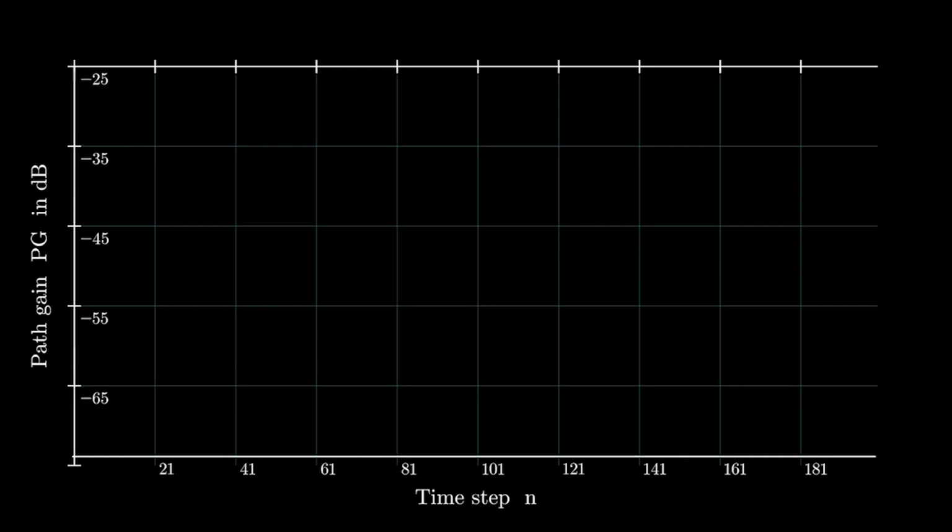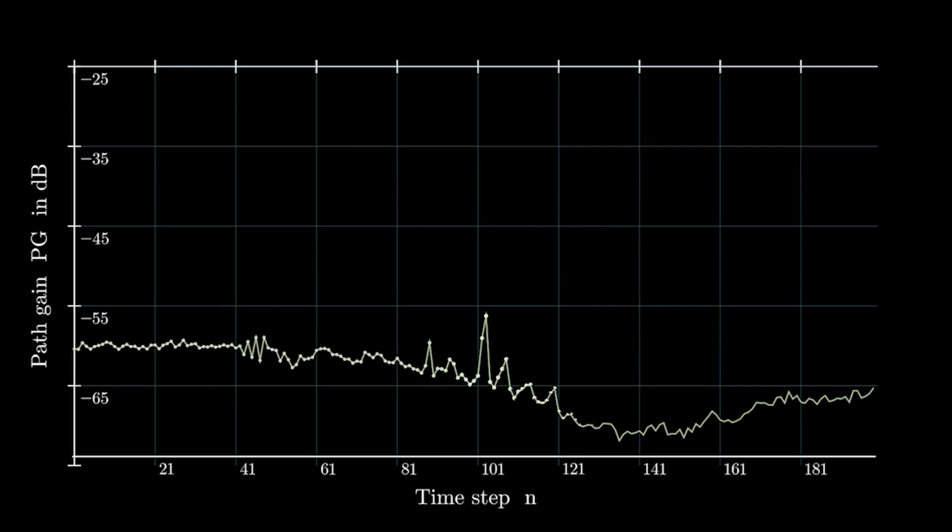The efficiency of phase-coherent beamforming depends on the quality of channel state information available. Having no channel state information, the statistically expected performance is the SISO efficiency, which is the baseline efficiency at which a random beamformer or an equivalent single antenna infrastructure would operate.